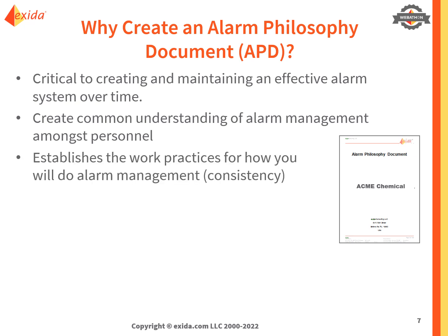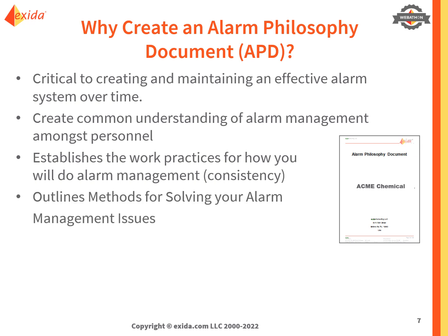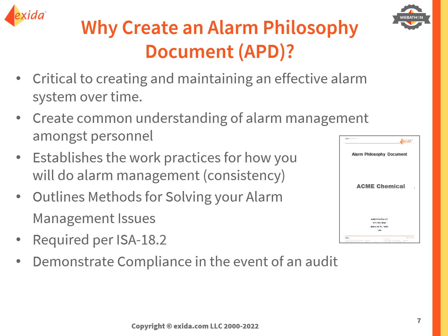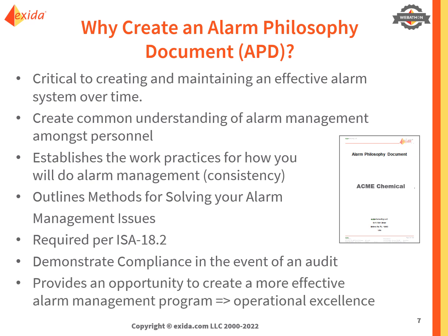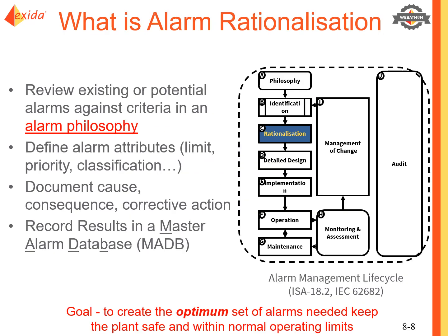It establishes how you do things and will do them consistently. It outlines the methods of solving alarm management issues, and it's required by ISA 18.2. And in the event of an audit, you can demonstrate compliance. It also provides an opportunity to create a more effective alarm management program, and that equals operational excellence.